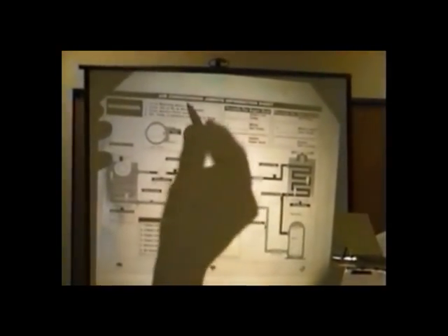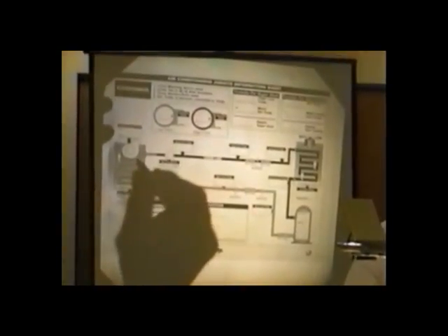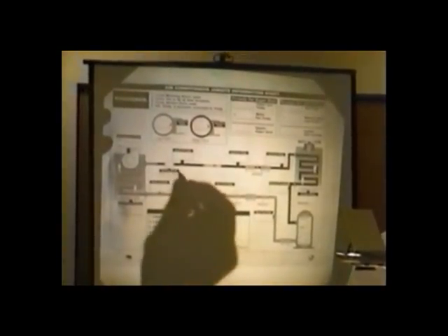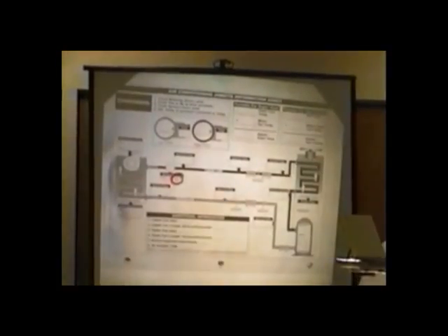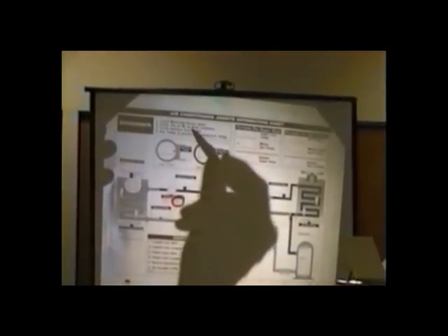It says circle the metering device used. Well, we know the metering device is before the evaporator. And so let's say we would circle fixed for an orifice. Then it says circle yes or no at dryer locations. Now watch this one. We know that after the condenser, we have a liquid line.